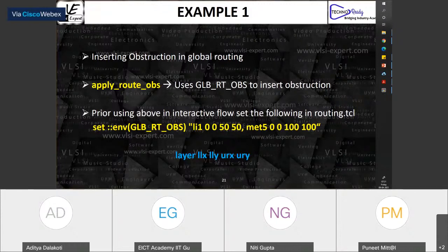Okay, how do we do routing over? Again, what do you mean by no gaps between blocks? That you cannot have blocks which overlap their pins. There is no way to create such blocks. You can have a block where a pin of one is just connected to the pin of the other, and that would mean that by abutment you have already done your routing.